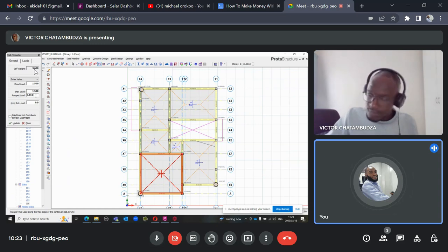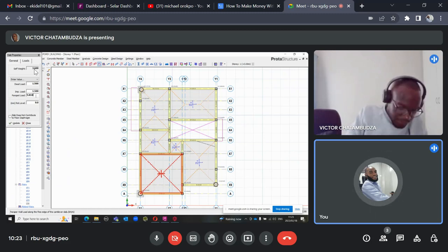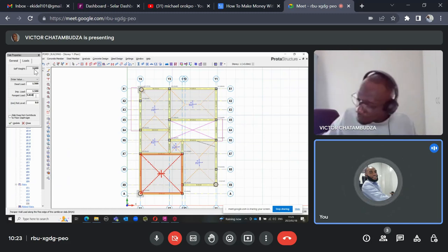So if you now add that to your wall unit weight, which is 2.87 plus 0.6, that gives us 3.47. That gives us the exact unit weight for one block. So this 3.47 is the weight that we use for design. We don't need to use the one of 2.87, because that 2.87 is the block weight without plastering, and knowing that there must be plaster on a block, we have to combine it together to have our own design unit weight, which is 3.47.